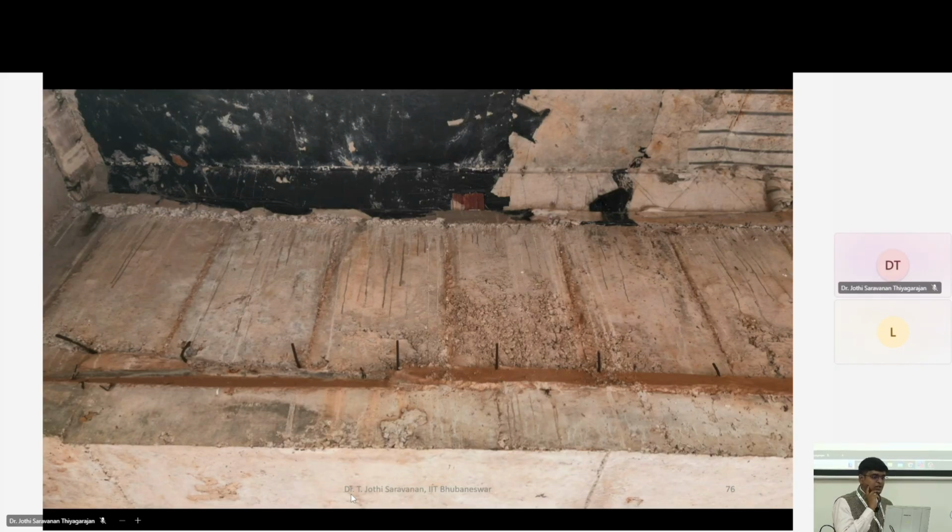Yes, so there are some extra bars which are not even cut. They have to be cut, and there are a lot of cracks, too many. In between each casting of the concrete, you can see that brown color, which is because of the corroded bars inside. That is coming out. Maybe during the rainy season you can see there are some leakages.